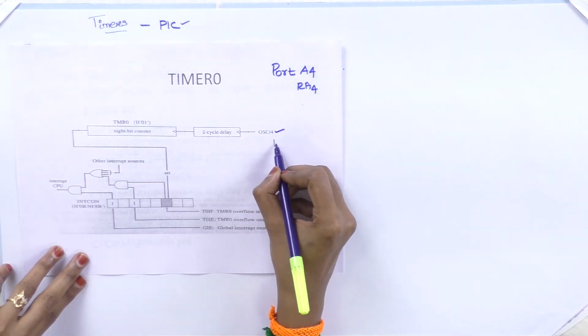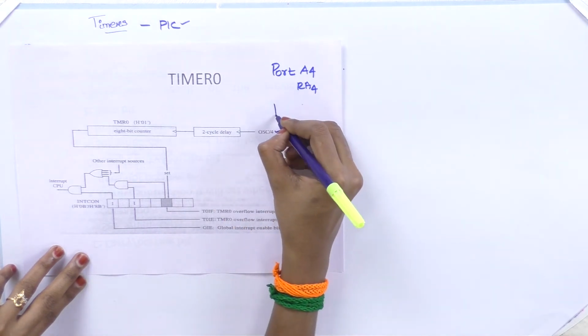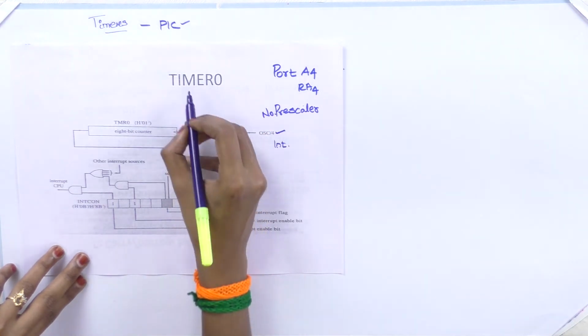So this timer is used for that function. At a particular time you can use it either for timer operation or for the watchdog timer. We can't use this timer register for both functions simultaneously; that is not possible. If you want to use this register as a watchdog timer, you should enable it. Unless it is enabled, it will function as the timer register. If you are using the internal clock, oscillator by 4, then there is no need for a prescaler value in timer 0.